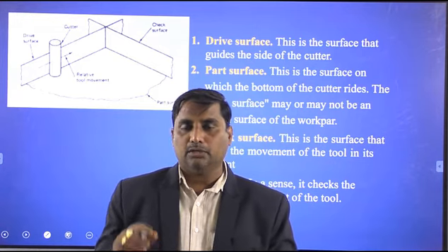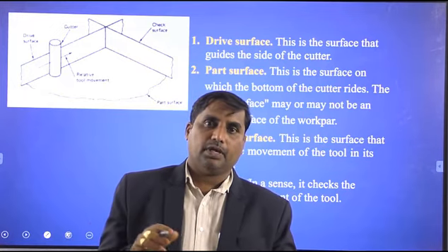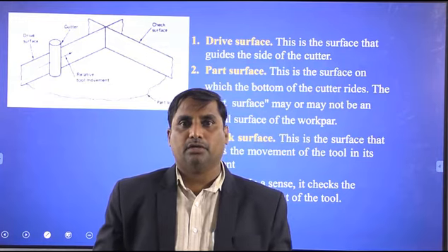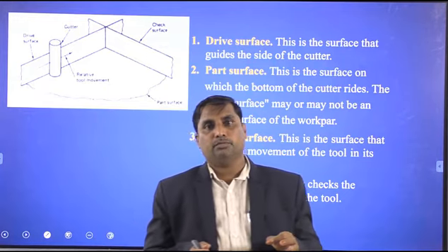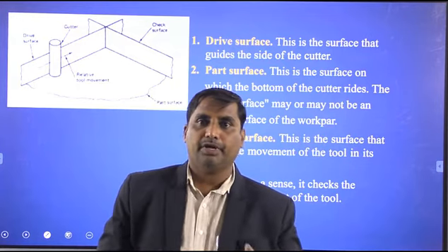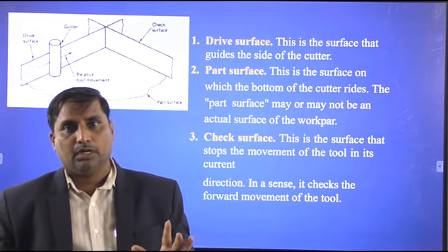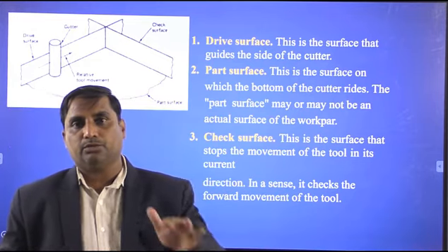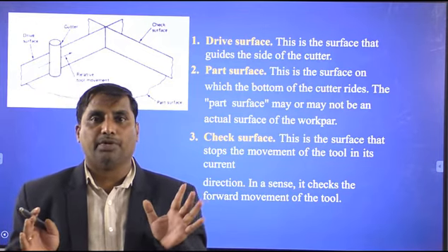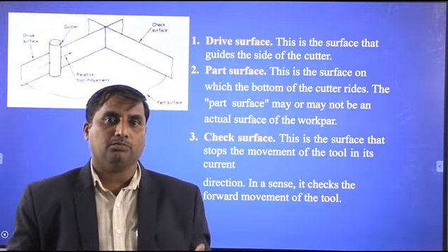Now, those are used for making general objects. Suppose there is a milling operation, a drill bit or cutting tool, not the machine tool. The cutting tool has to move in a different curved path in a specific direction and remove the material. In a general way, it has to move and remove the material. Those operations are called contouring operations, and these operations are performed by specifying different